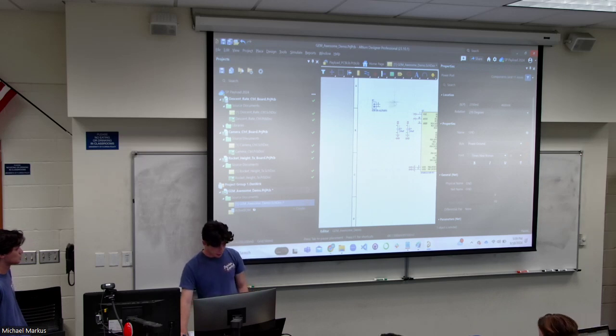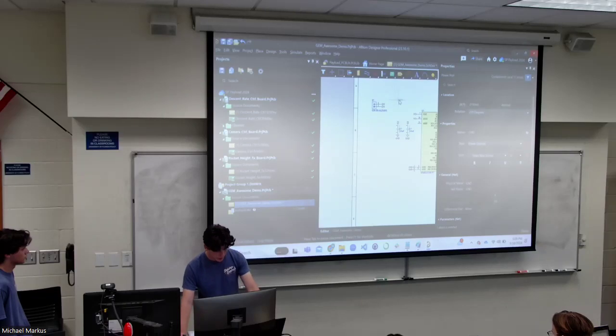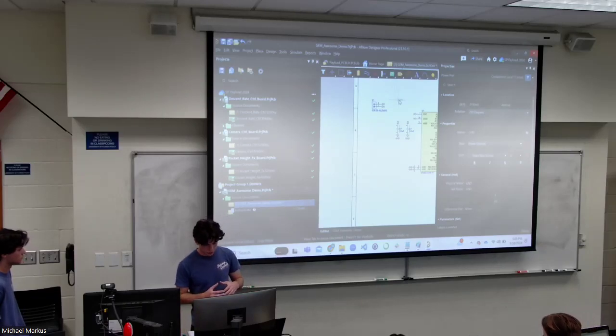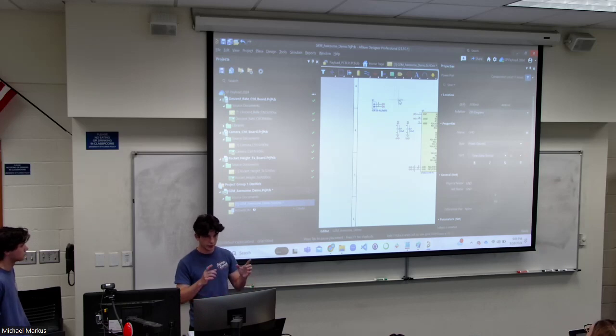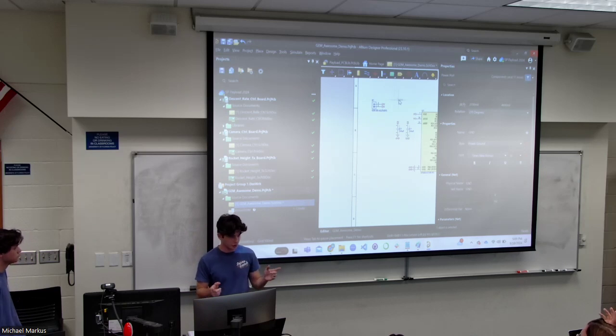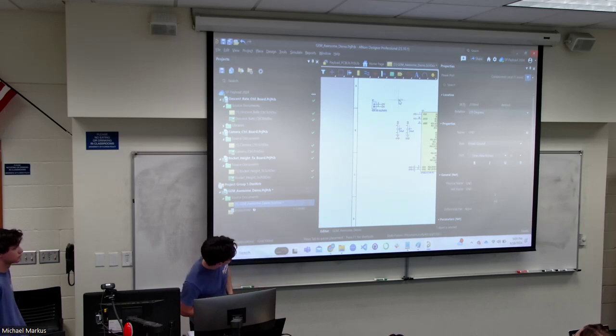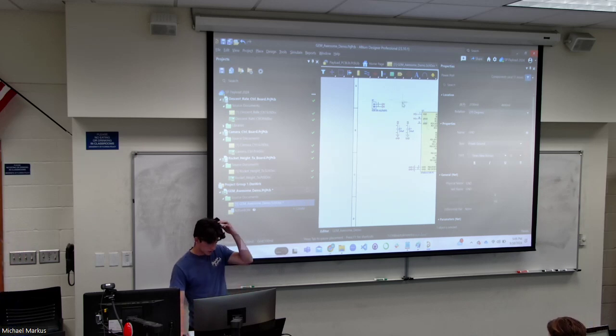And additionally, these pins over here, one is to input 5 volts and one is if you want to get your 5 volts back out. So we'll have those two here. What this does is it connects them in the software's internal logic. So you'll see when we go to the PCB, there'll be little lines going between the pins of the components to show you the stuff. You hit tab, and then it takes you to this properties menu, and you change the name. And then you also go to style, and you change it to bar.